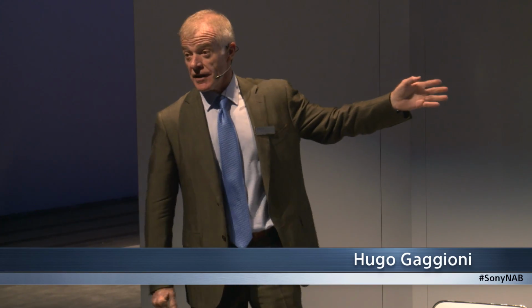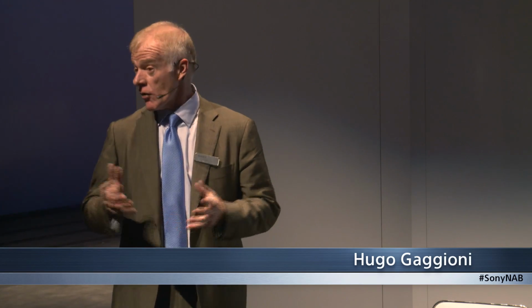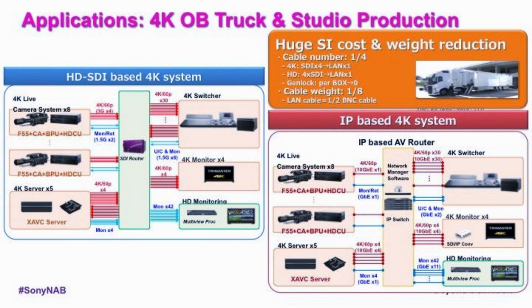This is an example of something that we lived ourselves. Last year, we built a truck that we used in the so-called Confederations Cup, and right now this truck is on its way to Brazil for the World Cup. The truck is completely using coaxial cable, and every single 4K signal requires 3 gigabit HD-SDI cables. You can imagine the amount of cable that we have in the truck. It is very expensive and weighs a lot. We can replace every 4 wires with a single fiber connection, which will reduce the weight of the truck dramatically.